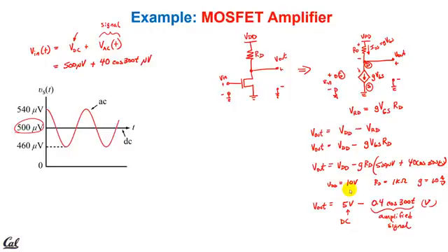Okay. So in an electret, what you actually have inside the electret, that little can, is a thing that's pretty much a capacitor, okay? Except here's the trick. It's a capacitor in the sense that it's got these two plates, right? But the trick is that when they're fabricated, the plates are made so that there's permanently trapped charge. Just so that there's charge stuck and embedded in this, and it'll last forever, basically. I mean, not forever, but a long time. And that's what's called the electret material. Yeah. It's usually some plastic or some insulator, usually a polymer that'll store charge, and you use tricks to get charge stuck into it.